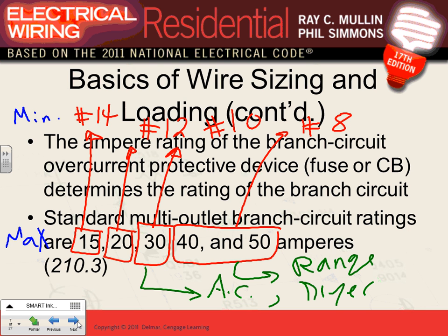Okay, the last thing, the last two circuits, these are typically, again, I'm saying typical. This circuit is typically lighting. Lighting circuit and general purpose receptacle. These circuits are special receptacles. Special receptacles, we use a 20 amp circuit, special locations like kitchens and so forth. Can I just get you to understand these four branch circuit that we use in dwelling? When we start laying out the building, that's what you're going to be looking at. Cool? Everybody can see the conductors?